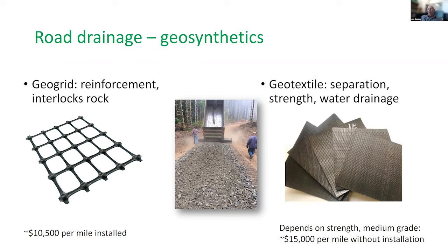And that was what I was going to emphasize as well, is that geotextiles are really appropriate for certain places, but once you put them in, it does change how you maintain that road, because as Fran said, if you're grading that road and the blade of the grader catches on that geotextile, you can rip the whole road out with it. And so if you've got geotextile down, you really need to be very careful about maintaining adequate gravel on top of it, and then maybe even identifying where that begins and ends, so that in the future there's no question about where you need to have a different maintenance procedure.